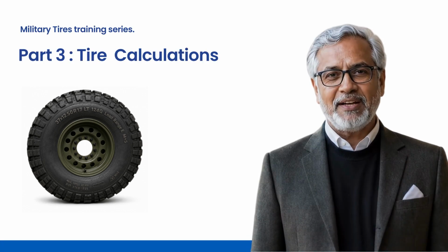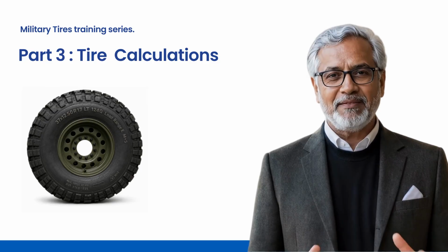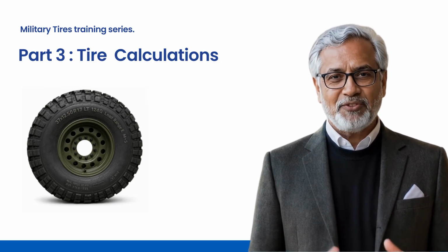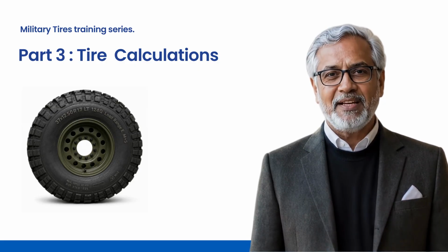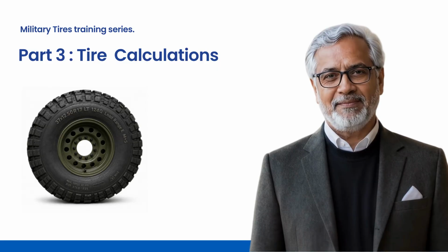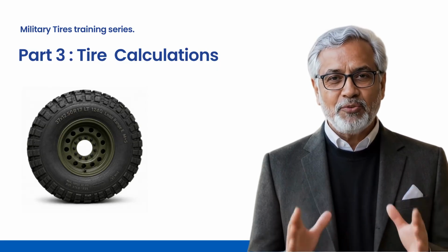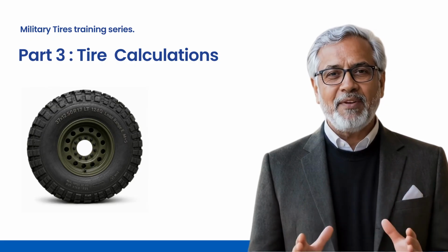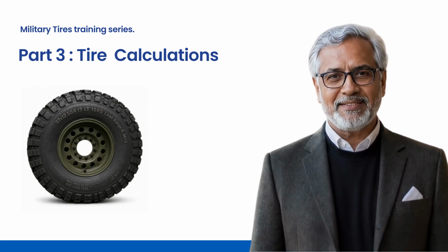Selecting the right tyre size is not simply about choosing a tyre that fits the wheel. It directly affects the vehicle's load capacity, mobility, stability, ground clearance, traction, and durability. A tyre that is too small may become overloaded, overheat, or fail during obstacle impacts.